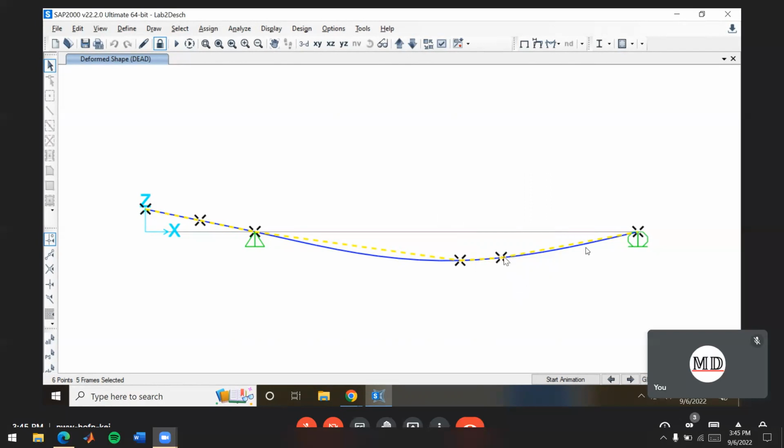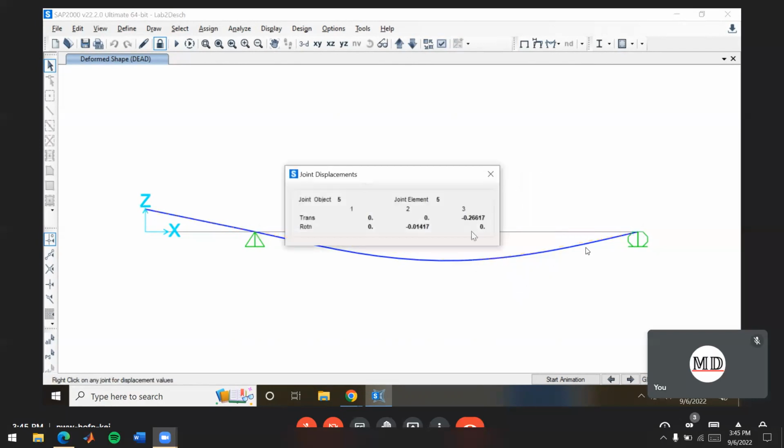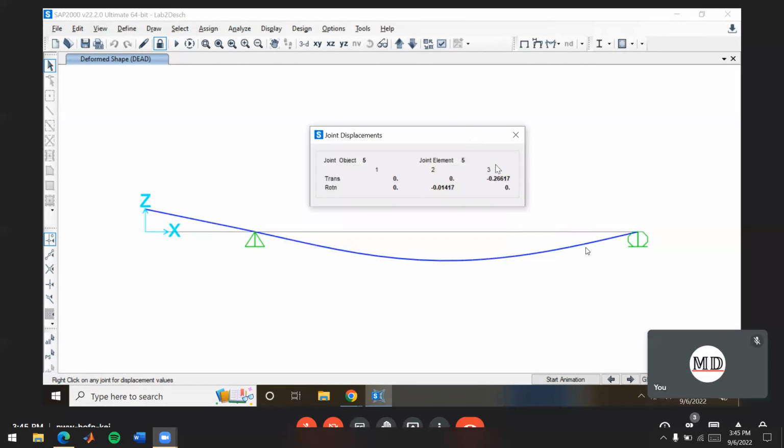Yeah. So that's the information we're looking for there. Now, to get these deformation values from these specific points, you need to be in the deformed shape to go and find those. There's other ways, but you need to go in like export tables and stuff too, and this is just the easier way to do it. Okay. Any questions on that?